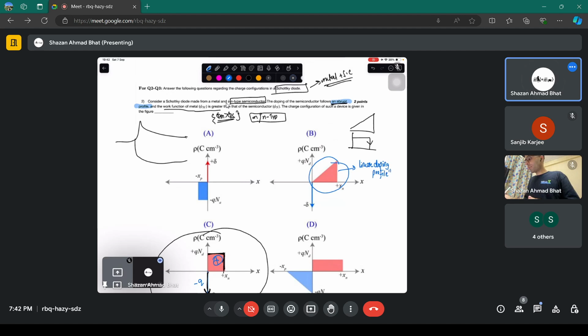Note that you only dope on the semiconductor side. You don't dope a metal because a metal already has a huge number of electrons. You dope a semiconductor in order to increase its conductivity and reduce the resistivity, because you know that conductivity is n q mobility. You increase the n, you increase the conductivity, from the basic Drude model. Simple as that. That's why you dope it.